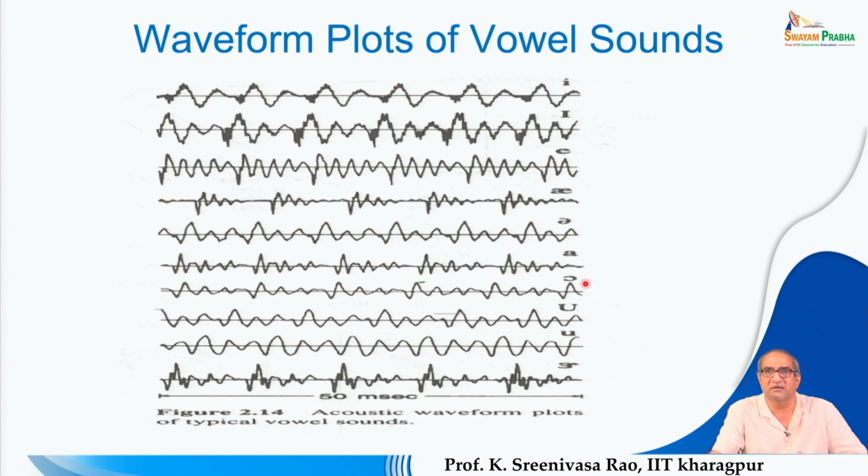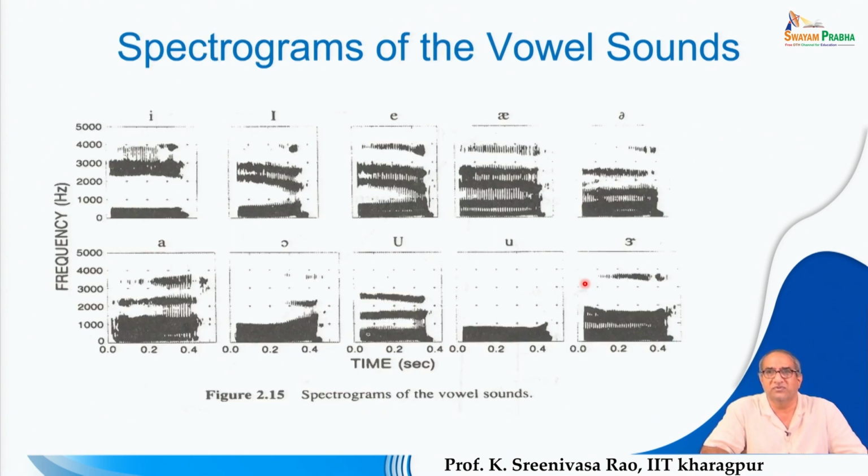So, this is just a broad observation from the time domain signals, whereas if you look at their corresponding spectrograms, you can see very clearly what we grossly observed in the time domain signals. In the case of A, as I mentioned, there are 4 or 5 formants here: this is the highest formant, this is the next formant, and these are the lower formants. You can observe that the bandwidth of the second formant, or the range of frequencies at the second formant, is slightly larger.